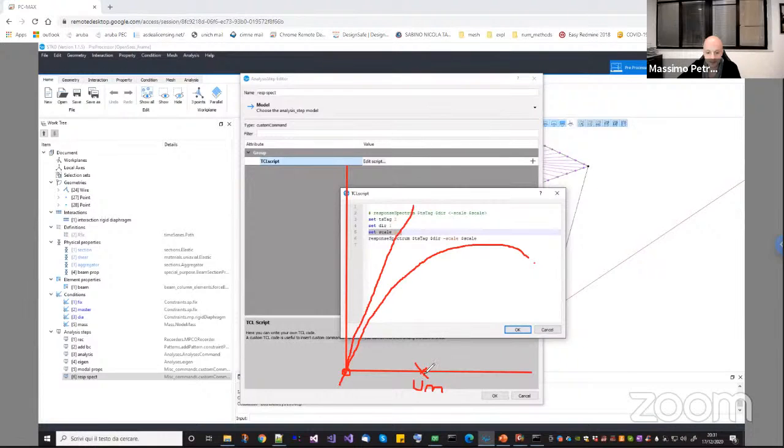So actually I would expect the output being this force, assuming a linear behavior. The problem is that when I plug this displacement inside OpenSees and I ask for the results in terms of forces, OpenSees will give me the nonlinear force, or even worse, it may not converge if this displacement is too large. So how do I obtain this kind of elastic force?